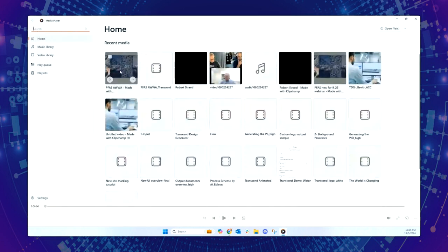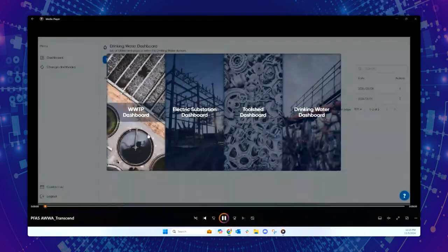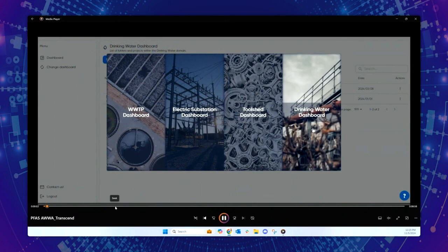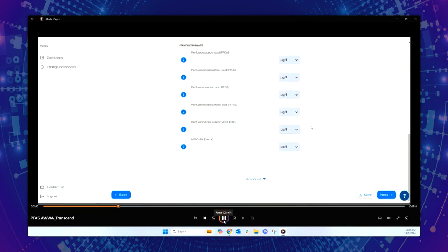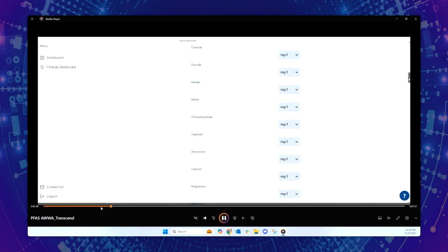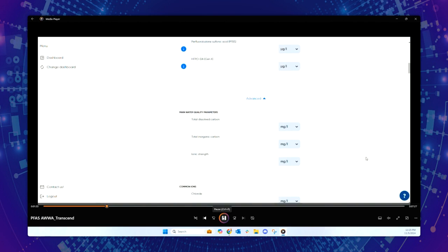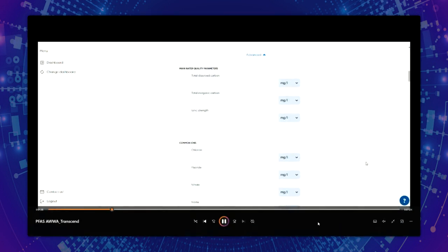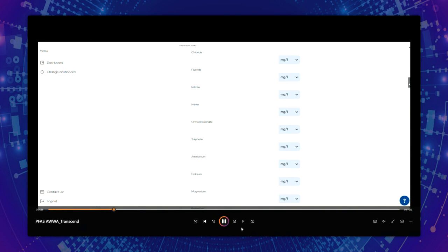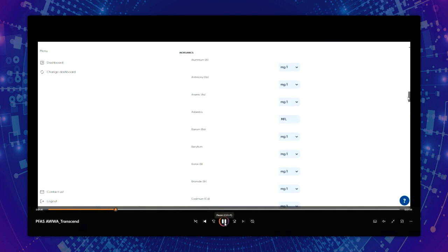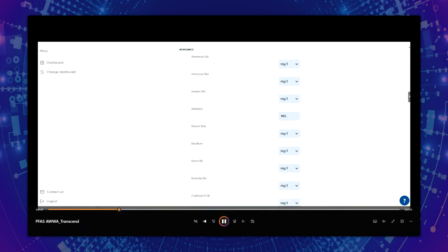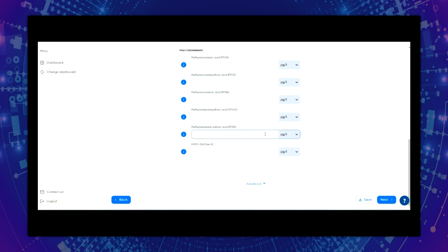So the input parameters are parameters that you typically have in your sampling protocols and probably with reporting to your regulator. The additional parameters are parameters that are maybe competing with your media. In case of media, some of those parameters may be 1,4-dioxane, or iron, manganese, additional chloride. Situations where your media will be competing against the PFAS, and so that could be disclosed in here. If you don't have them, you could leave them empty. No, that wouldn't cause an issue.